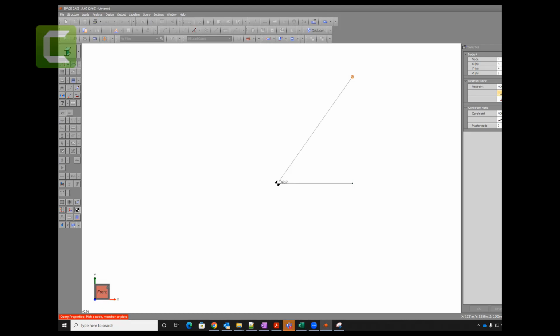So if I hold something very tight, the point, I'm talking about the point again. The student asked me a question. You remember that we need to have this point. I'm talking about that point being fixed in all directions. There is a pin here that fixes all the displacements. You can see the first 3 displacements are fixed. There is a rotation fixed about the x-axis, but the rotation about the y and the rotation about the z are allowed.